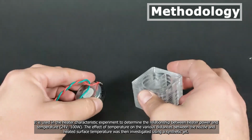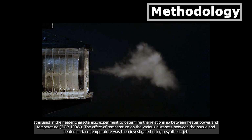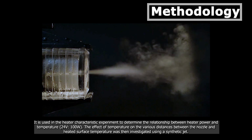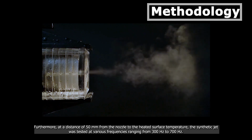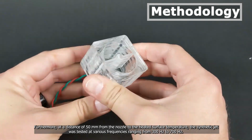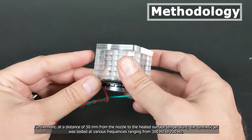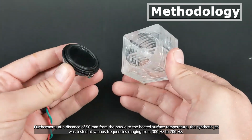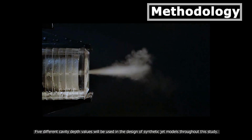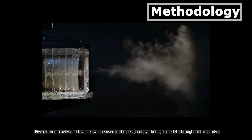The effect of temperature on the various distances between the nozzle and heated surface temperature was then investigated using a synthetic jet. Furthermore, at a distance of 50 mm from the nozzles to the heated surface temperature, the synthetic jet was tested at various frequencies ranging from 300 Hz to 700 Hz. Five different cavity depth values will be used in the design of synthetic jet models throughout this study.